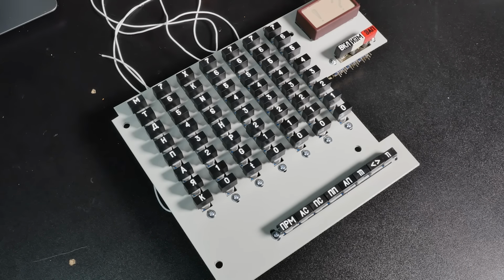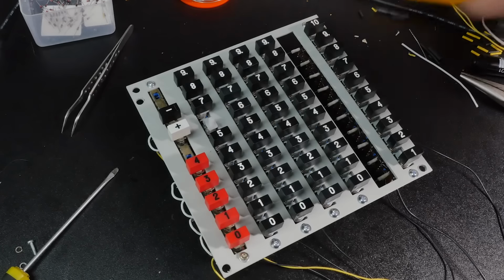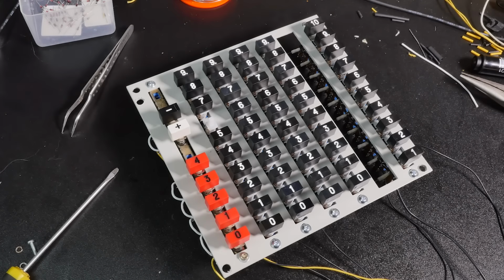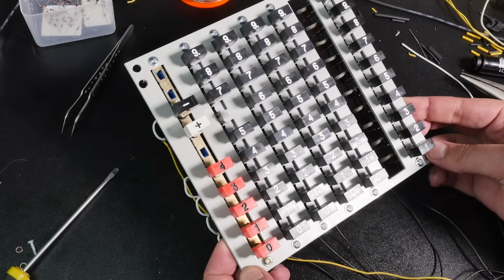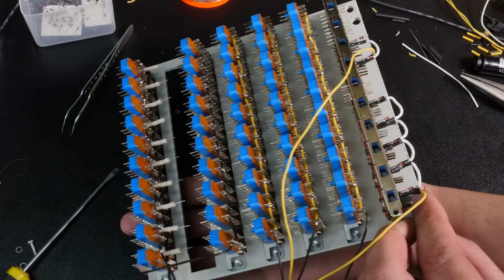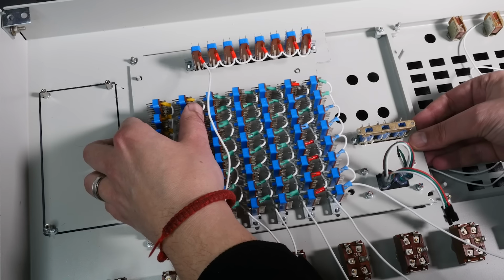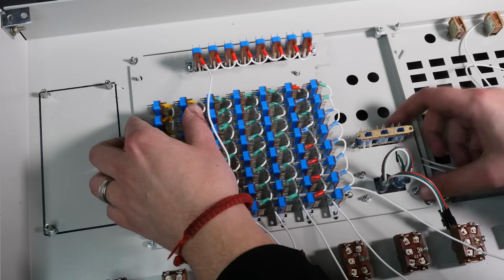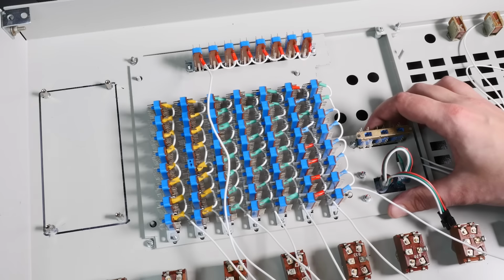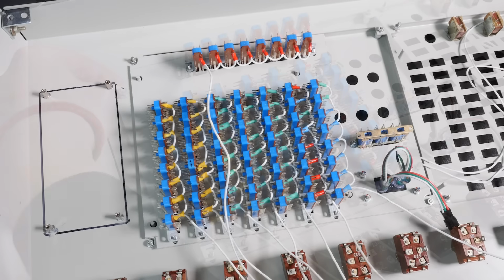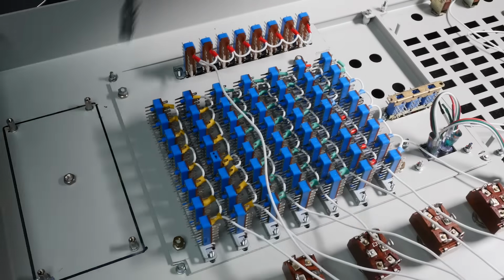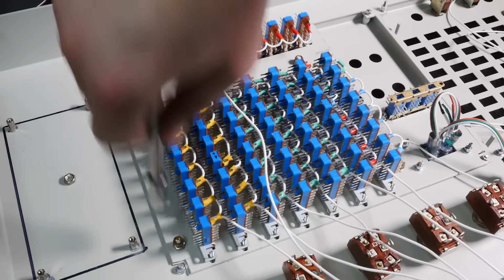Then I wired the keyboard switch blocks. The original keyboards are electrically arranged as matrices, so first I created common electrical lines for all button columns. Later I also added the lines for the rows, but at that moment I just didn't want too many loose wires getting in the way. And then these complete assemblies went inside the housing, and I began securing them with nuts on the mounting studs.